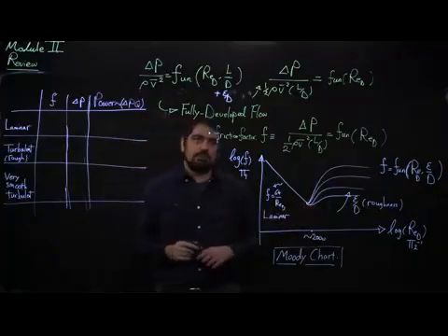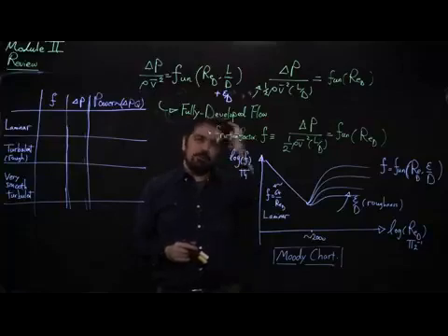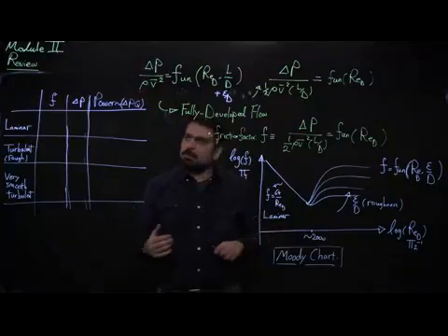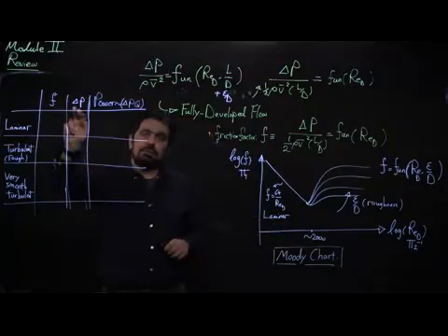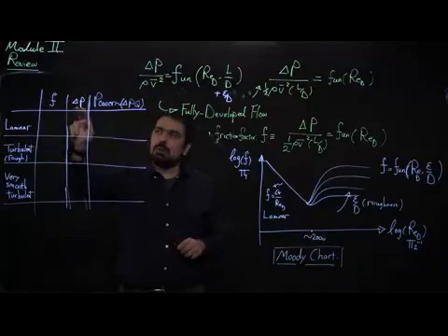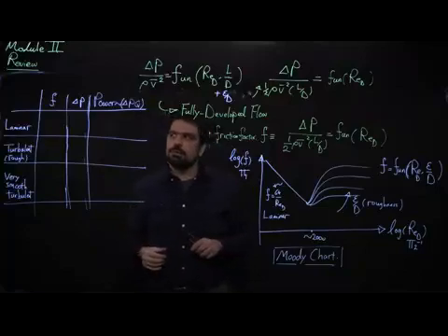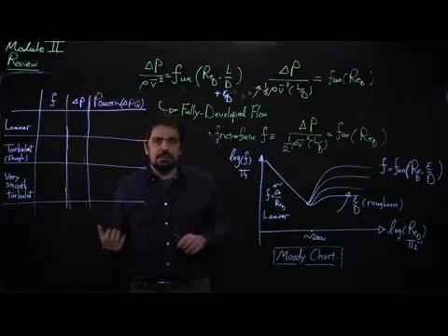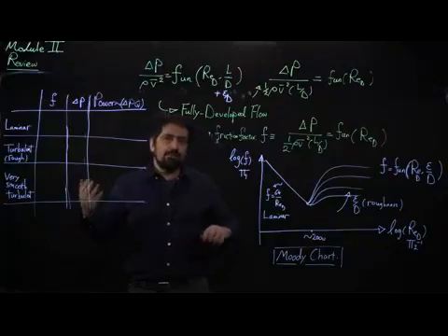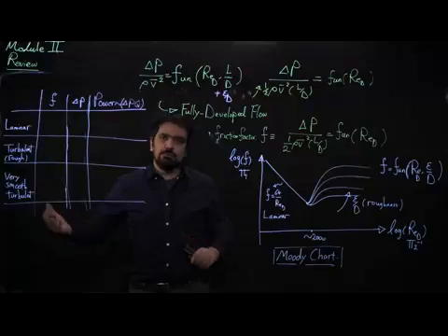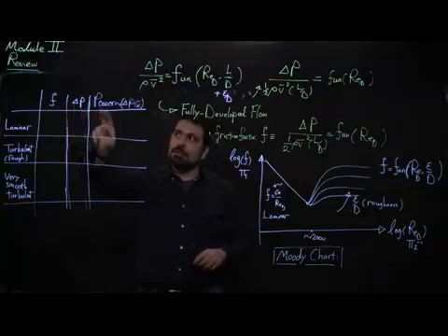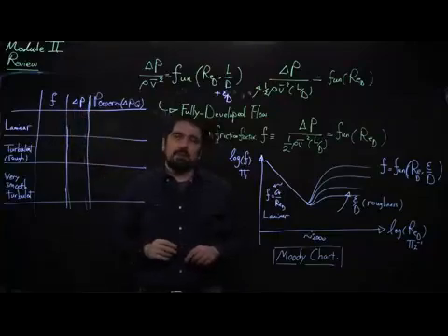Let's say, for example, you're controlling the flow rate and you want to see how the friction factor varies with the flow rate. But more importantly, in real engineering applications, you usually think about, for a given flow rate, how much pressure drop you are facing or how much pressure drop you should provide. So the delta P required to have that specific flow rate is something that you want to find, whether it's increasing with flow rate linearly. Is it increasing as flow rate to the power of 2 or 5? If you multiply the flow rate by a factor of 2, how much extra pressure do you need to drive that flow? And maybe the other parameter that is very important is the power of the pump.